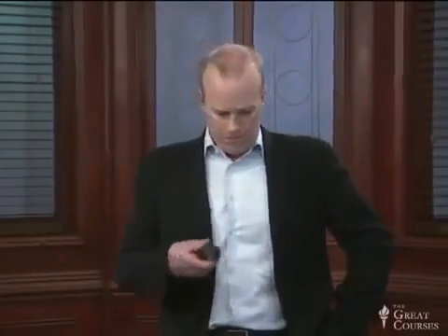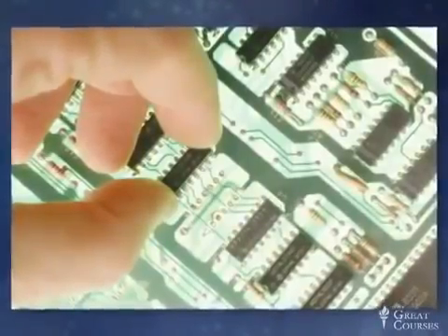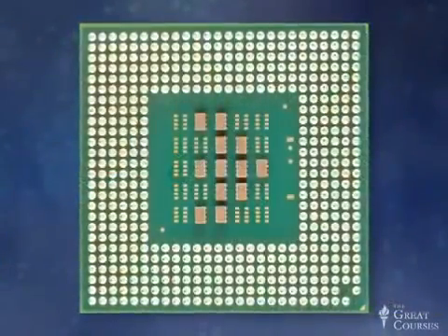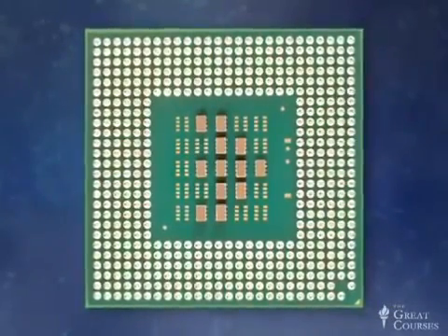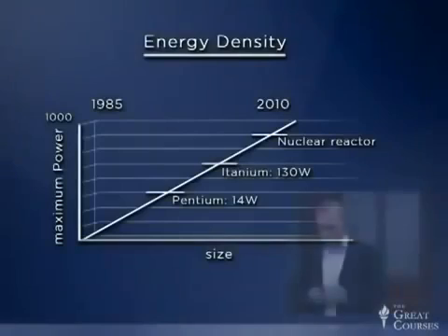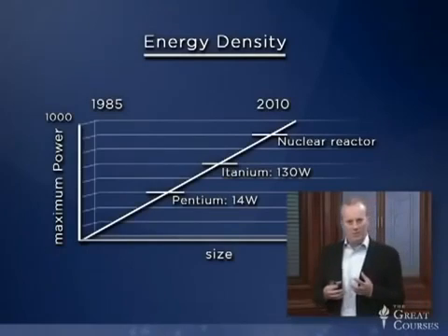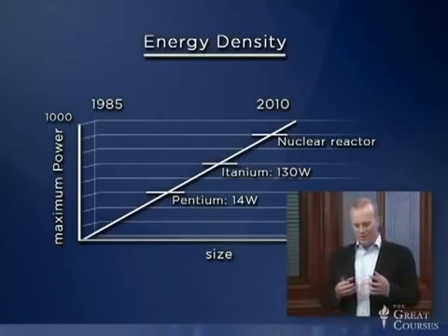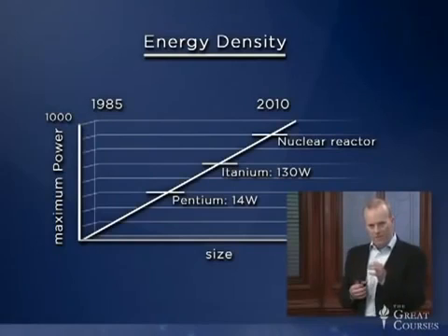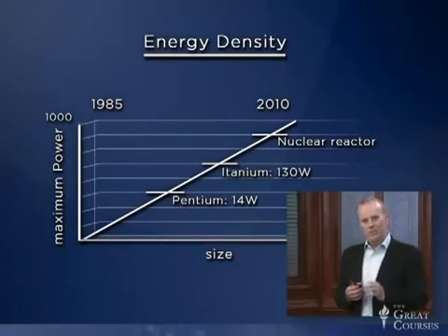Why is this almost an inevitable trend, an important thing to do? We talked during our discussions of the field of electronics about how as we make our chips smaller and smaller, we put more and more energy density into a given region of that chip. In fact, it's amazing. If you look at the evolution of the energy density of integrated circuits, we're only a few doubling factors away from having the same energy generation density in the very most active part of an integrated circuit as the energy density inside a nuclear reactor. And so we're starting, as we shrink and shrink and shrink in the field of electronics, we're moving towards a denser and denser generation of energy.